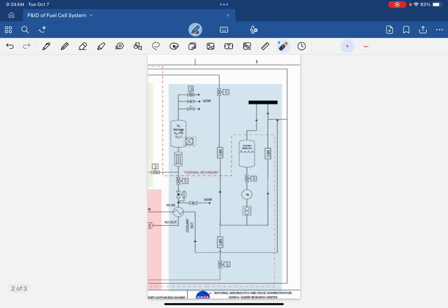I have a smaller picture of this actual section so it's a little easier to see. We're going to start on this side. Even though this is right outside the section, it's important because this is how hydrogen flows into this portion of the section. The only way it can flow in is by this ball valve, which has a solenoid actuator.